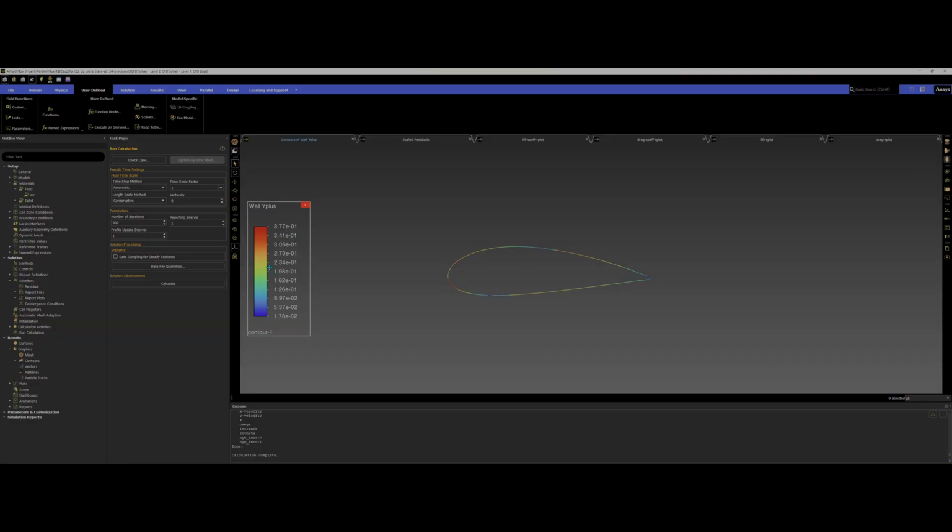That is good. I always target a y plus under 1. If it's greater than 1, like if it's less than 4, maybe you can get away with it, maybe around 3. But any greater than that, then your results will be way off, and you should not trust your simulation. But a y plus under 1 is great, it's excellent.